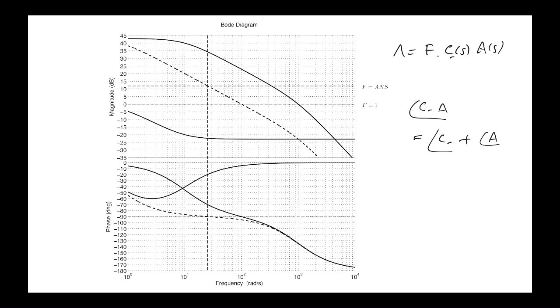So the point here is that the lead compensator has helped us achieve a wider bandwidth than would be achievable with a lag compensator, for the closed loop. These are just examples showing you how to read things off Bode plots. There are exam questions like this, so it's worth getting your head around it all. Are there any questions before we have a look at the exam?